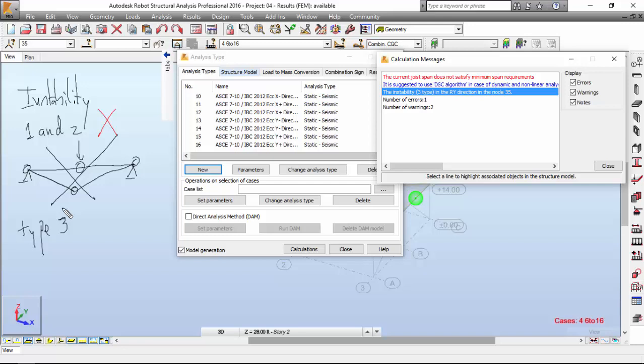Okay, if you model your structure this way or in a certain way, and you are certain of the way you are modeling, you may ignore these type 3 instabilities. Okay, if the results and the displacements have nice values, you may just ignore this, as I'm going to do right now, and then we will explore the results for bars, and if we find something odd, then we should take a look at this type 3 instability. Okay, for now I'm not going to do anything.